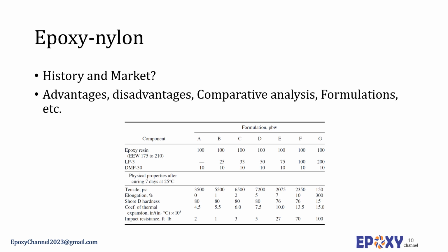The degradation by exposure to moisture occurs with both the cured and uncured adhesives. Not only is low tensile shear strain noticed on moisture aging, but also the mode of failure changes from one of the cohesion to adhesion types. Substrate primers have been used with epoxy nylon adhesives to provide improved moisture resistance. However, they do not achieve the moisture resistance associated with unmodified epoxy or nitrile epoxy adhesives.